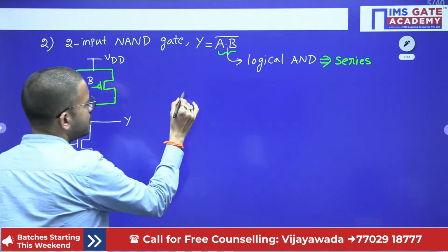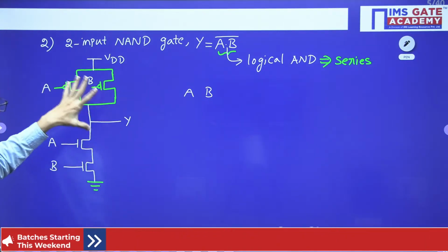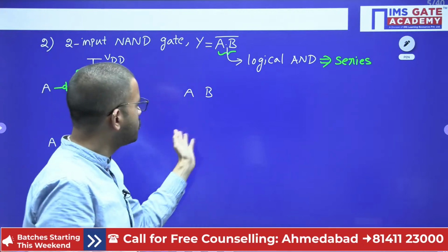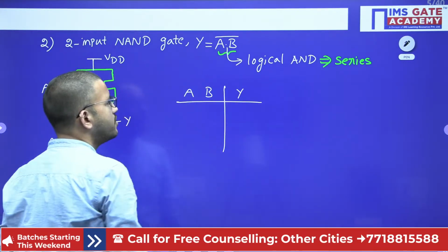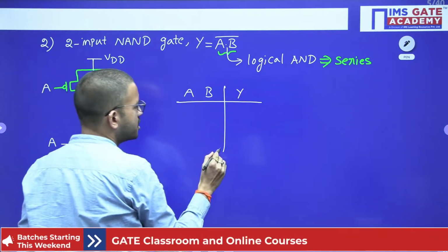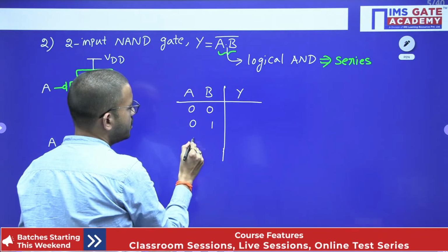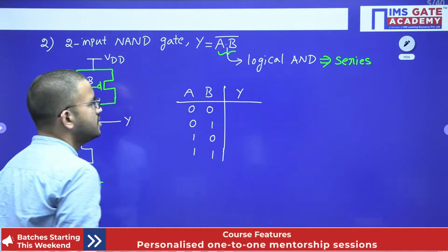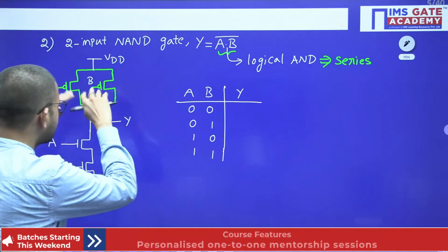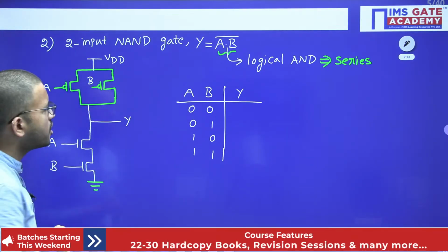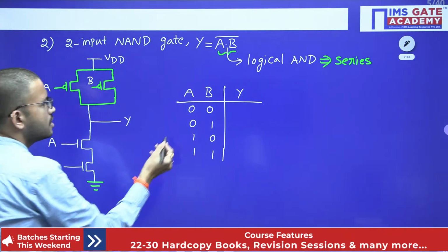Okay, right. Now since you understood clearly regarding the NOT gate operation, regarding NAND gate operation, directly we will take with the values, zeros and ones. When you are having 2 bits or 2 inputs, you will get 4 combinations of zeros and ones. So just note down all the 4 combinations: 0 0, 0 1, 1 0, 1 1. These are the 4 combinations at the input side. Now let us analyze what kind of output this particular circuit is producing for each and every combination. So now just observe the initial case, in which both are zeros.